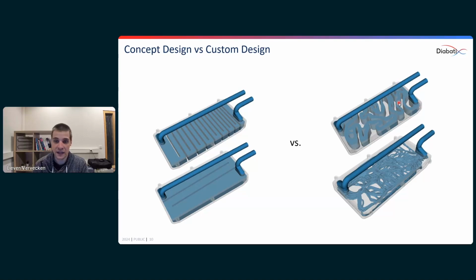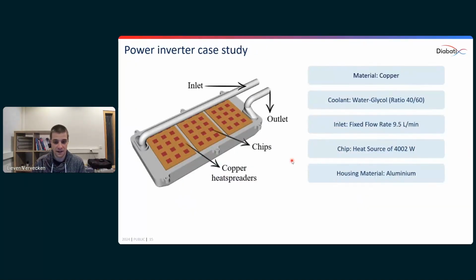For example, here on the top, CNC milling was used, so it's a more conventional manufacturing technique. But even with that more conventional manufacturing technique, the shape or the pattern, the cooling channel that's being generated is very complicated. It snakes through the entire space. If you then go for 3D printing, where you also allow for flexibility over height, you get a true spaghetti of cooling channels within your design domain.